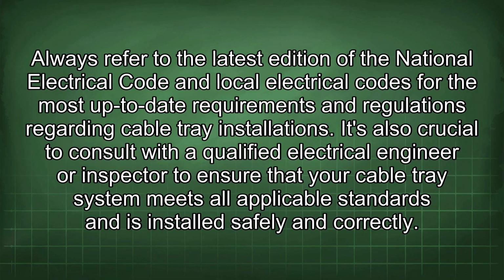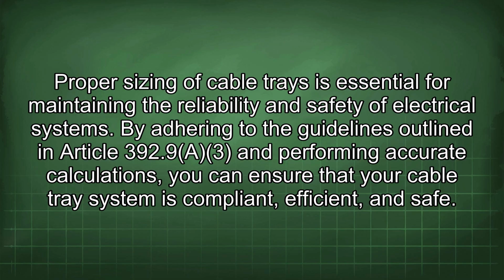It's also crucial to consult with a qualified electrical engineer or inspector to ensure that your cable tray system meets all applicable standards and is installed safely and correctly. Proper sizing of cable trays is essential for maintaining the reliability and safety of electrical systems. By adhering to the guidelines outlined in Article 392.9 A3 and performing accurate calculations, you can ensure that your cable tray system is compliant, efficient, and safe.